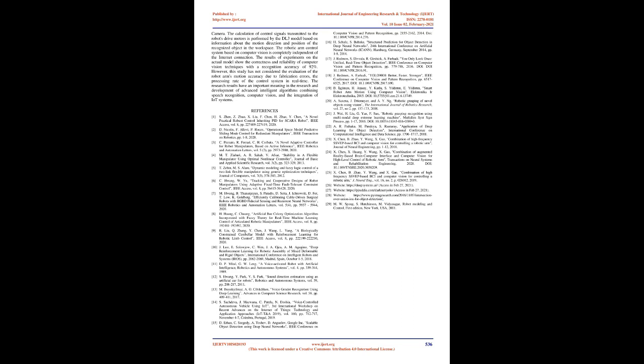Control result. The DL3 network parameters controlling the robot are shown in Fig 13 with 5 outputs corresponding to 5 rotation angles of the robot joints. The network consists of 9 hidden layers with the ReLU activation function. The number of nodes per layer is presented in Fig 14.